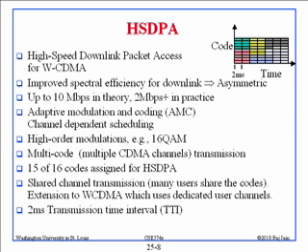OFDMA plus the CDMA something. So we have the frequency and time, but we also in each sub-channel we do a share code or something. What we are saying is, can we do OFDMA with CDMA? Yes. And that is called multi-carrier CDMA, where each subcarrier has CDMA on top of it. Yeah, that is done. Actually, in that case, generally, because each carrier is so little, 10 kilohertz, you might have bigger carriers, then you won't use little carriers. But all combinations are possible, yes.